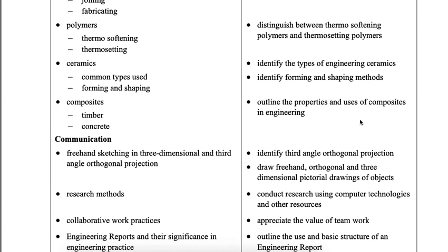So number 1 is PET. Number 2, the plastic's so nice they named it twice, is HDPE. Number 3 is PVC. Number 4 is low density polyethylene, so the shrink wrap. Number 5, the challenger like Rocky, is polypropylene. Number 6, polystyrene. Polystyrene's probably the one that's on a bit of the way out.